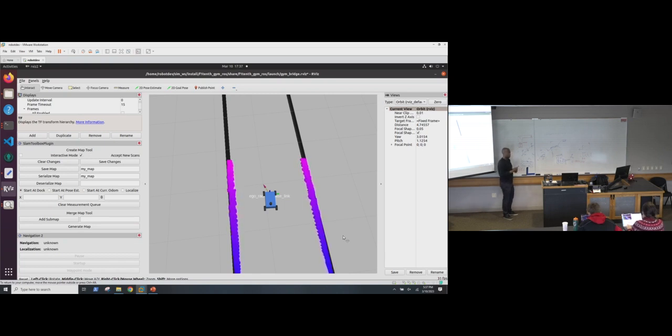I was just wondering if there's ways to fine tune it, because obviously one algorithm isn't going to work for all robotic use cases. No, yeah. So a lot of it is the parameters, like how big that box is for the obstacles. If you make it too tiny, it may say cannot reach goal, or when you try to compute it, it would time out. So you need to figure those out. The algorithm could work for anything, but the parameters are what make the algorithm work for that environment.